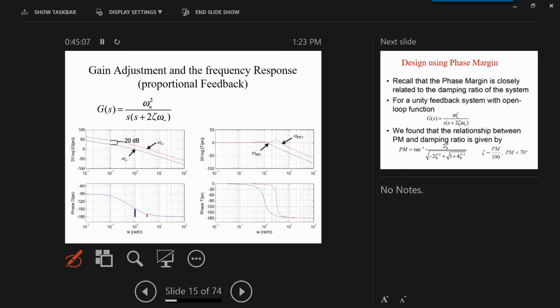I have a pole at the origin, and a second pole at s equals minus 2 zeta omega. If you don't know how to do the root locus, as I have seen many not able to do in the multiple choice question with the pole at the origin and the pole just like this and different options, many people selected the wrong one. So this is the root locus. It goes toward this breakaway, and it goes here.